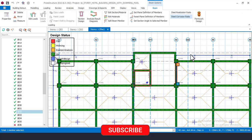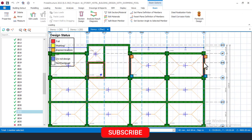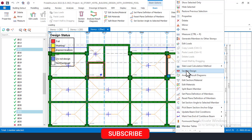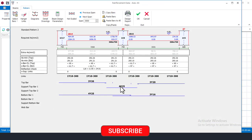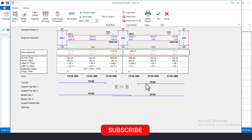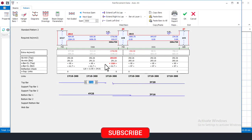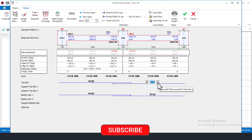I'll come again right now, this other side now, go here, we are having just one beam left. Come again right now, click on this, right click here and then click on this one here and then check again and then come first, remove this bar first entirely, make sure I lap first to control the bending moment there, and then come again here, lap again here and then increase my bar number to 4 and then to have it, and then this can be decreased to, let me see, okay, this is okay.